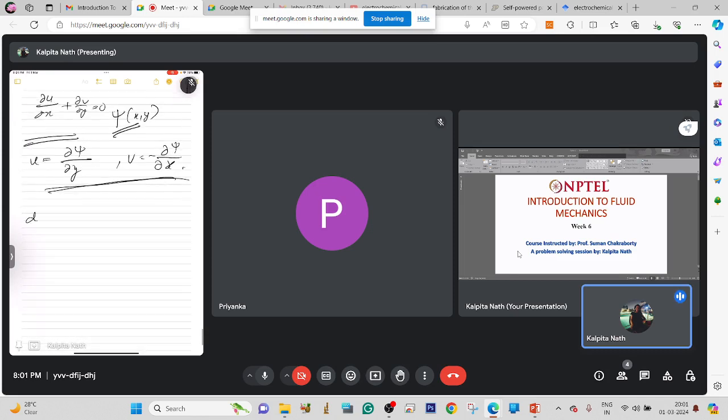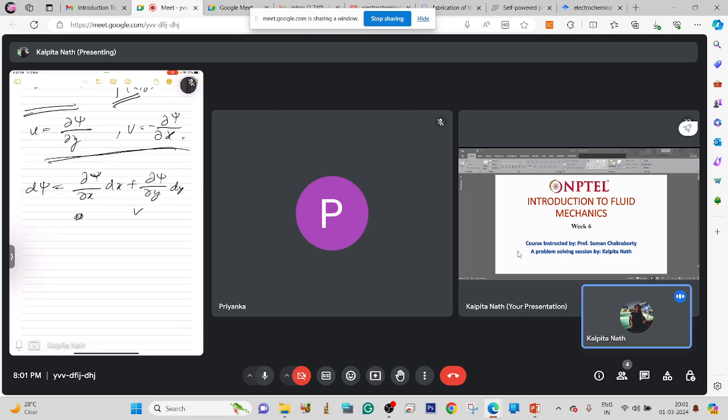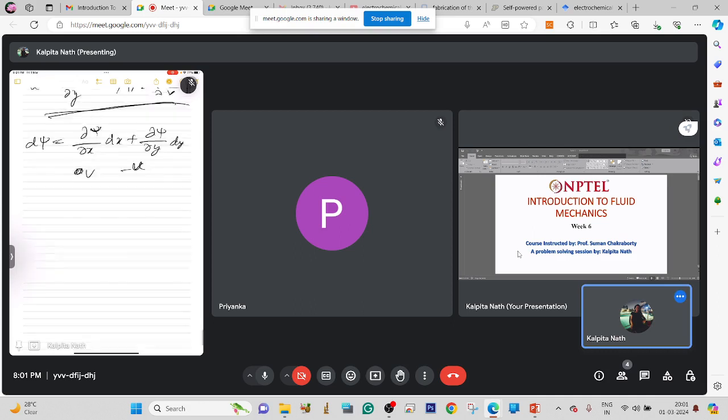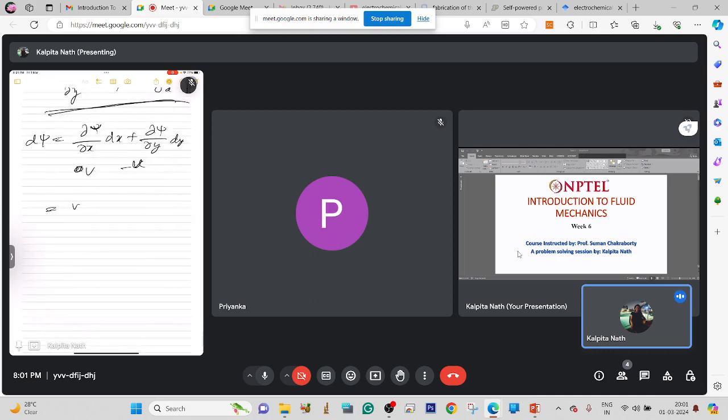So d psi will be equal to del psi del x dx plus del psi del y dy. That means this is v, and this is minus u. So this is equal to v dx minus u dy.